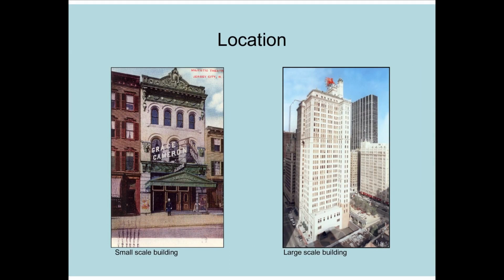The overall visibility of a character defining material or feature is an important determinant in whether a substitute material will be appropriate. Generally, the more visible a feature is, and the more important it is to the building's historic character, the more likely it will affect that character. A replacement cornice using a substitute material proposed for a two-story building would have to match more closely the historic element than one intended for a 10-story building.